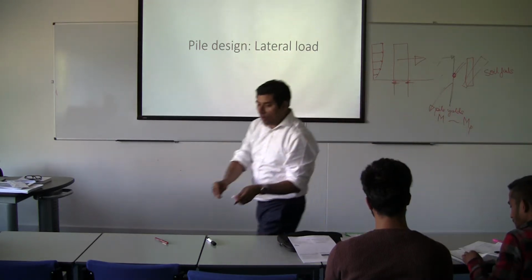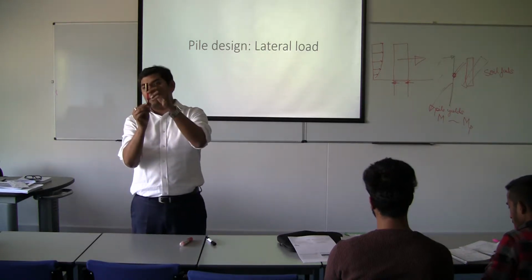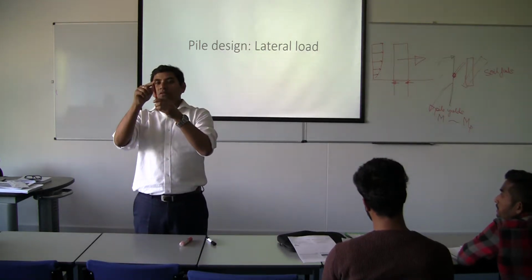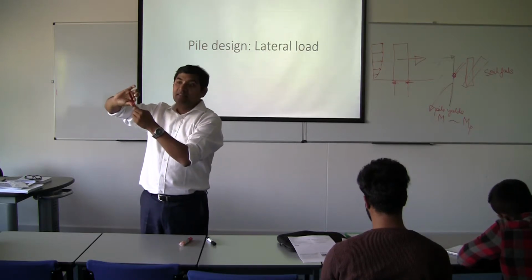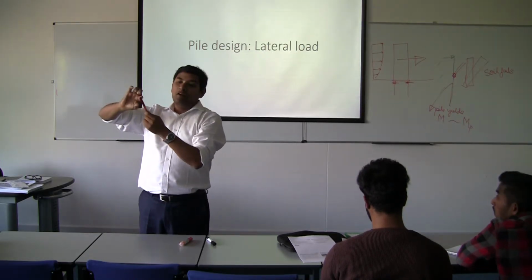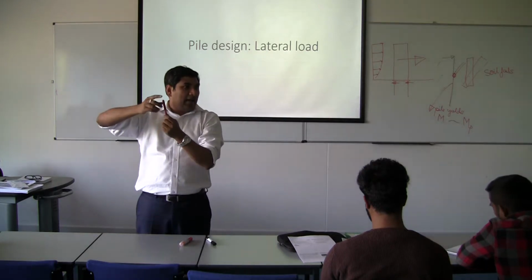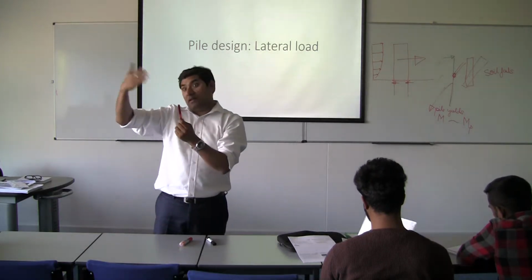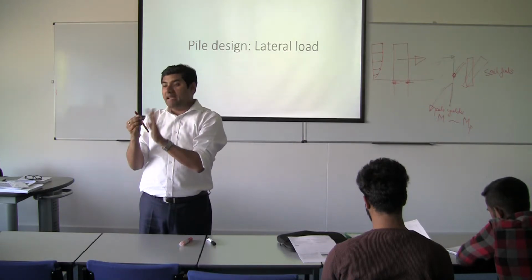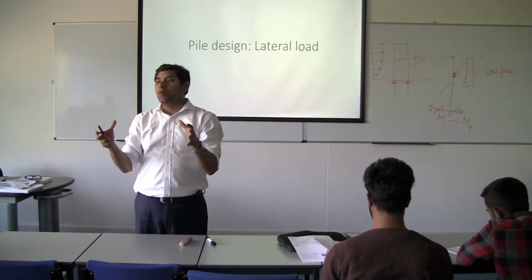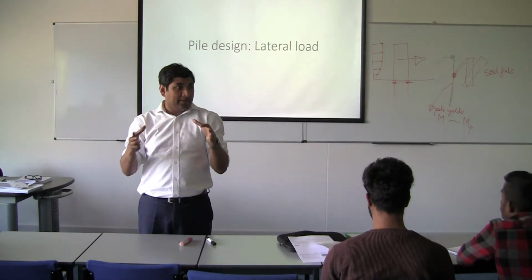Like in these sort of long pile cases, as you apply the load, the pile would have a bending, it will start to bend. As it bends, there will be strain forming, and if the movement increases to a limit, it will form a plastic hinge. Right? So you will calculate the bending moment and compare with the yield moment, how much that thing can take.